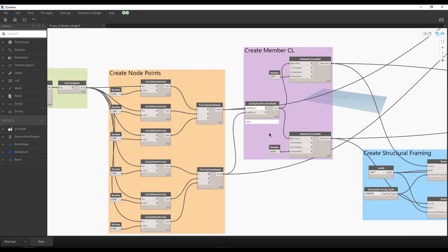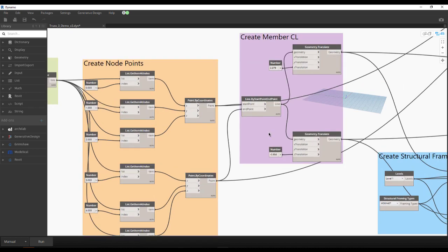Probably what we'll do as we go further along in design is pull that out and have those as offsets in a particular input area. So it's more of an input for the user, so that they're called out, so we can make those changes quickly if needed, based on changing members, those kinds of things. It could also be an equation based on CGs of members. As those change, we can automate that so that it automatically puts that center line in the right location.